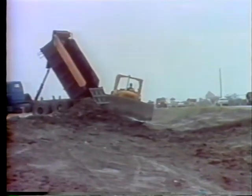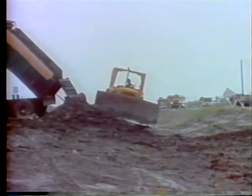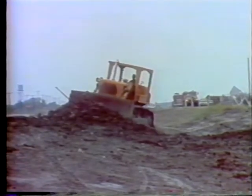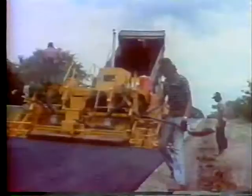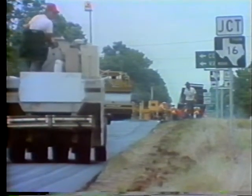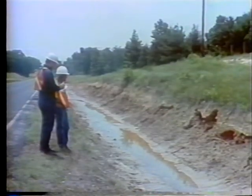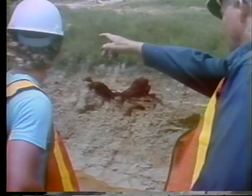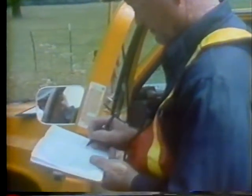The upgrading of unsafe ditches, slopes, drainage devices, and pavement drop-offs should be coordinated with many other maintenance and construction activities. To provide a systematic improvement, make routine inspections and keep accurate records of findings, comments, and recommendations. After the work is completed, add to the record a description of the improvement and when it was done.